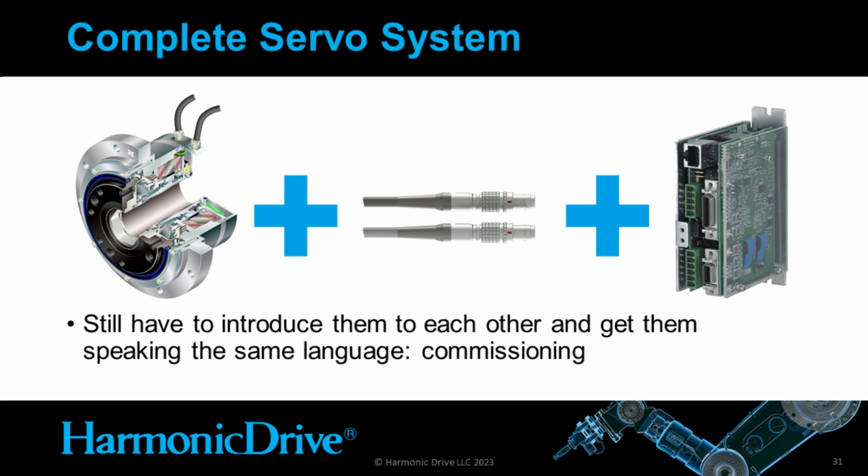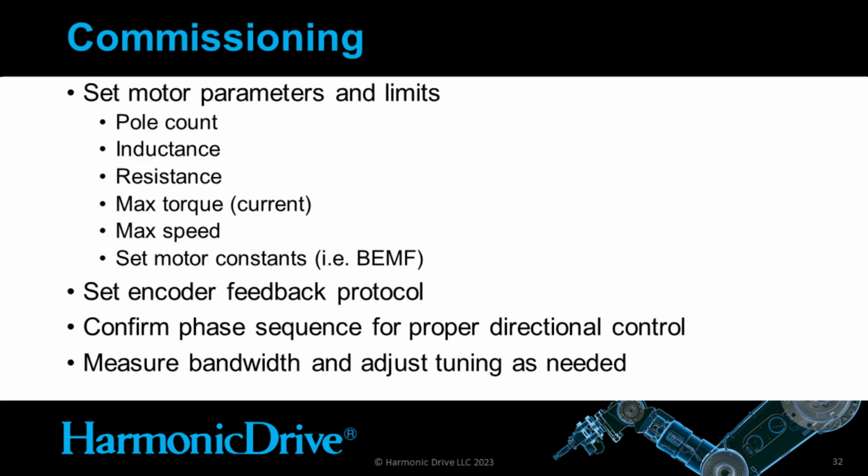So this is the entire servo system. We have the actuator on the left side, the servo drive on the right side, and in the middle we have cables that connect them. But this does not mean that we're done after we've designed and selected all of these components and put them together. We still have to introduce them to each other and get them speaking the same language, which in the industry is known as commissioning.